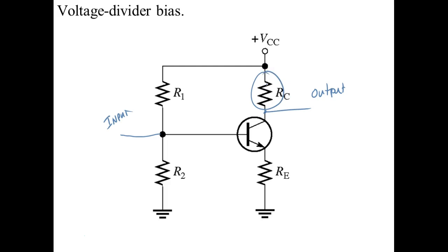So we've got a current valve, but we're trying to get some type of gain. Normally, this is going to give us a voltage gain. Well, if I've got a device that gives me nothing but current, then to get voltage out of it, I've got to put a fixed resistor in series with it, right? So the fixed resistor, RC, is actually what's developing the output voltage. RE is in there for temperature stability.